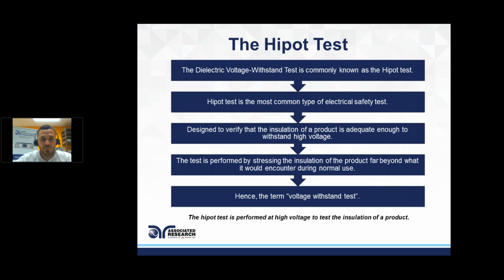So first, let's begin with the Hipot test, okay? It is called the dielectric withstand test, dielectric voltage withstand, dielectric strength test, Hipot, which obviously stands for high potential, and I believe in Europe it's been known to be called a flash test. Hipot test is the most common type of electrical safety test.